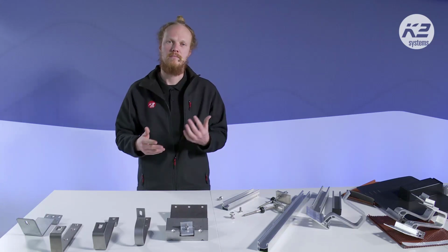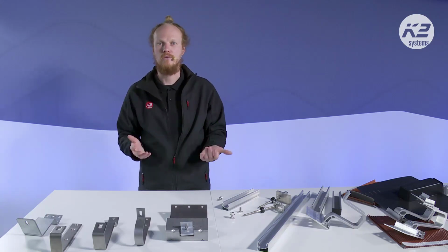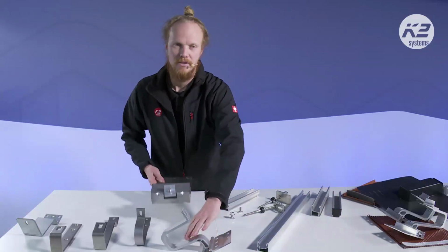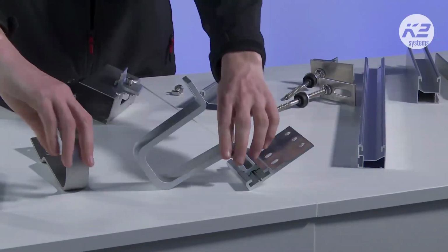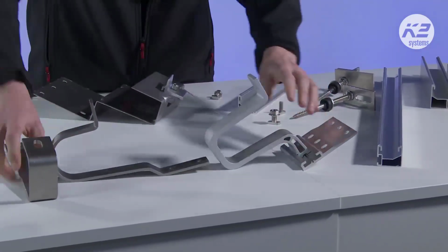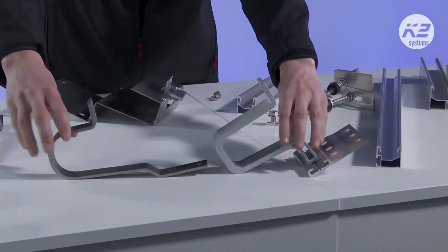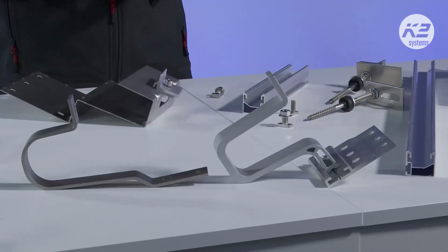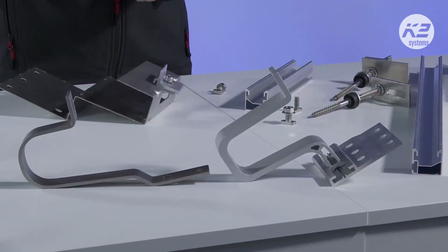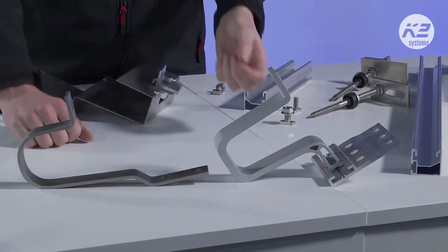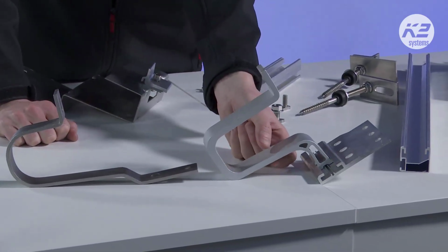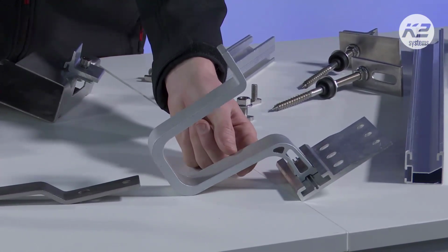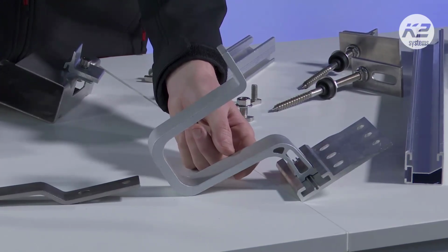But one of the downsides of that is that they're usually quite thick. Just as a comparison, I have a single hook which is made out of aluminium here, and if we compare that to a single hook which is made out of steel, you can see the thickness difference. For the flat tiles, this thickness difference can be quite an issue, because you don't have so much space to play with, and you can't mill the tiles out, as we've spoken about before. So you might have to replace the tiles, which is one option.